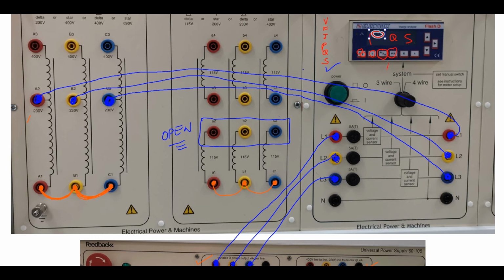This button here shows our power factor. Okay, this is for the energy, and this for time. Okay, the ones that will be used in our lab will be those 4 parameters here, 4 buttons. Keep in mind we have to calculate power factor, but let's display it here and calculate it at the same time, and try to compare your power factors. So this is for the feedback and three-phase transformer tests, open and short circuit. Open circuit for the three-phase transformer in the feedback station.